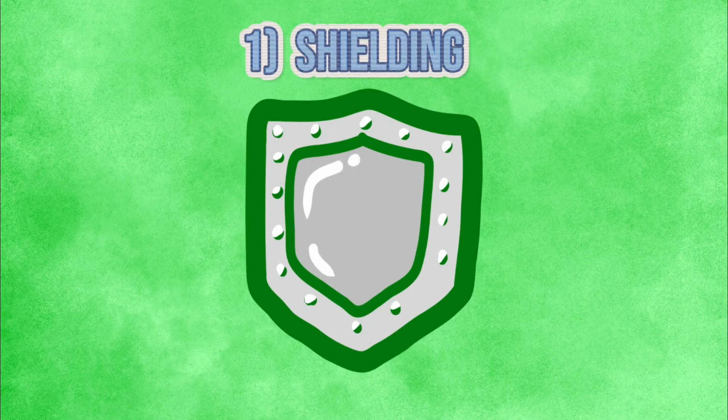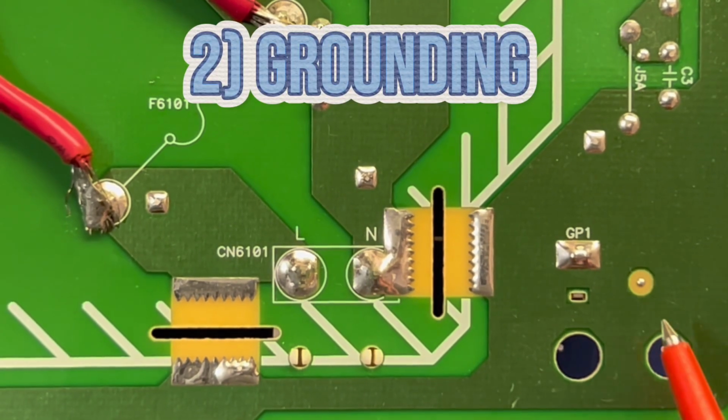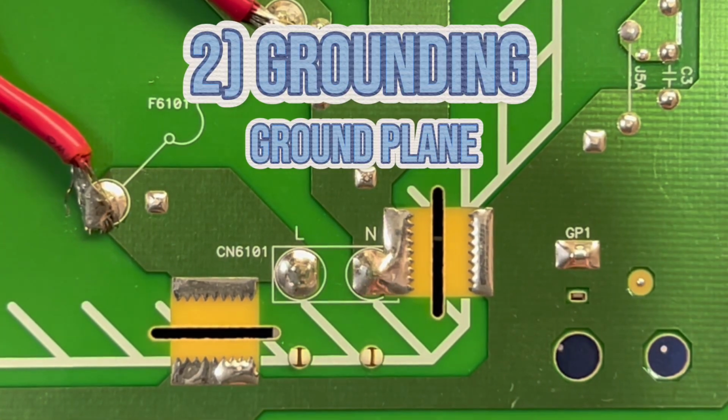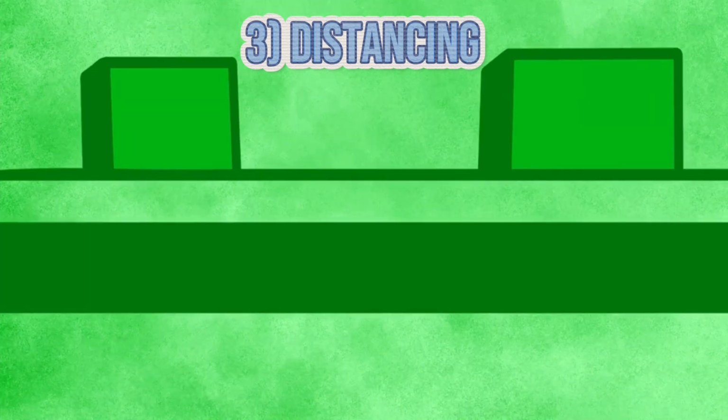First, shielding. Shielding is simply isolating circuits. This can be done with shielding cans and layers. Second, grounding. This yellowish layer is a ground plane. Having a continuous grounding plane allows a low resistance path for EMI to exit. Third, distancing. Short signal paths and closeness to ground planes mitigates EMI.